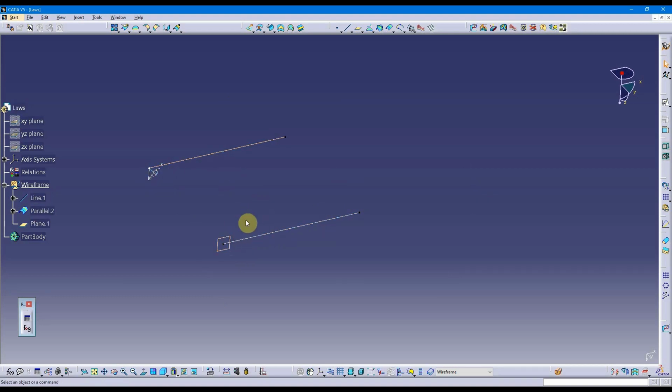And what I'm going to do is create my sine curve and my cosine curve with the parallel curve tool with the use of laws. So the primary demonstration here is of how to create a law properly to use for that parallel curve tool. So let's begin here.